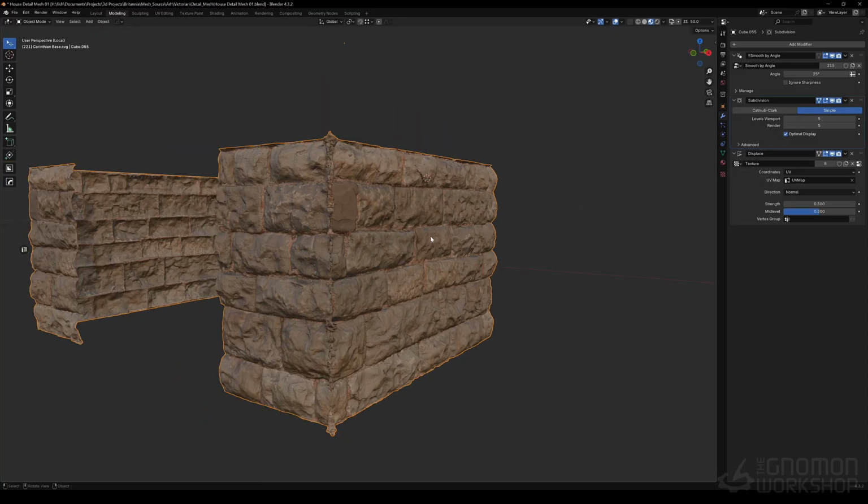Now, most video game engines are going to give you the ability to do displacement in the engine, but I try to steer clear from doing displacement in video game engines, because when you are building out a level, one of the first things that is going to get optimized down when you get into the optimization stage is displacement. The engineers or the designers will come to you and say, we got to turn off all the displacement. There's too many polygons. We're putting too much load on the renderer to do all of this polygon division on the fly. Therefore, displacement usually gets cut very early on in the optimization phase.